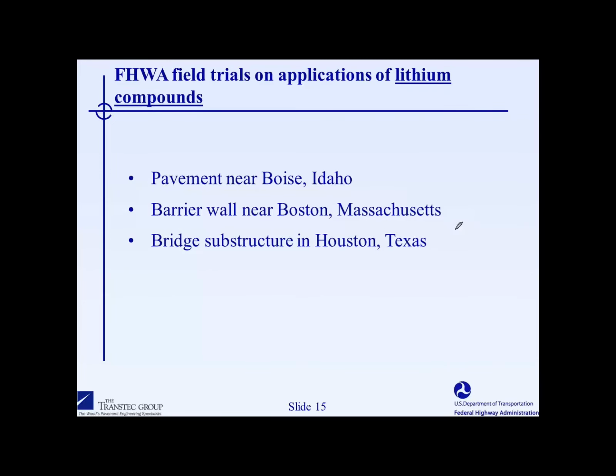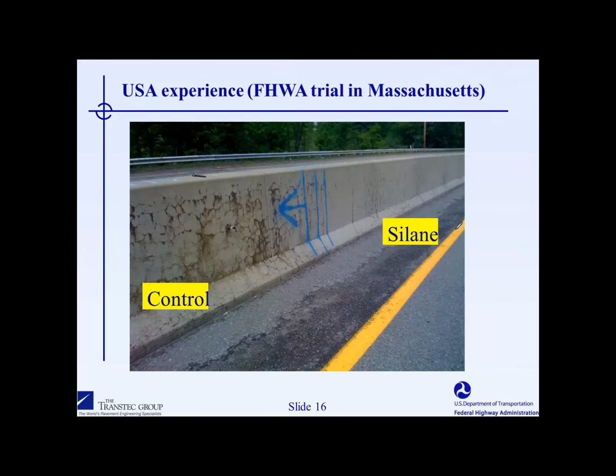Now, silanes will not always work. We know that for sure. If it's concrete below grade, there's very little you can do in terms of making silanes work well. And we're not sure about other situations.